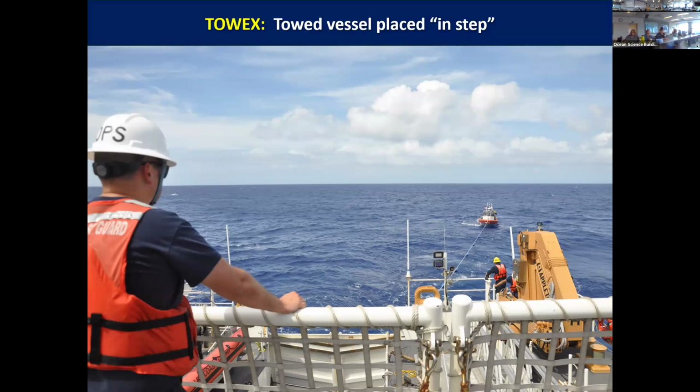So it's tricky. You have to go do it slow. And then how you pick up speed. You just don't at this point just, okay, all ahead. You can't do it. You have to slowly work it up. You have to turn slowly with vessels under tow. So all of this just requires room. So for me as a cutterman, when we talk about spacing, if you're going to talk about big ships offshore that I might have to go into with a ship to rescue, I'm going to want and need as much room as I can. I would always ask for that because that just gives me maximum flexibility. There may be times I see a vessel in distress and go, sorry, I can't get in there to tow you. I'm going to have to wait till you drift through that field, come out on the other end. And that's where we're going to have conversations about, will they come off their vessel?